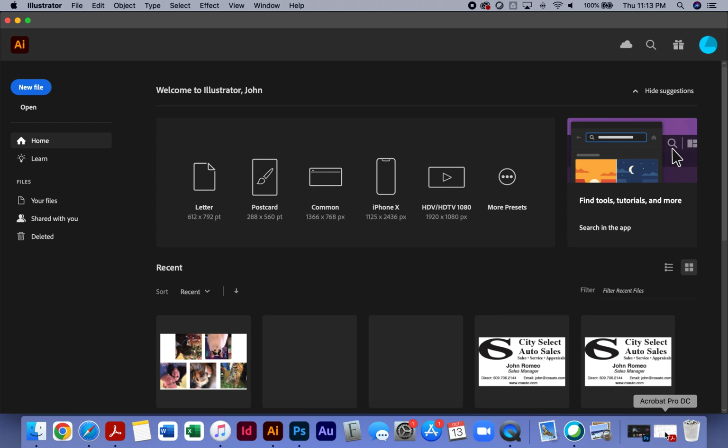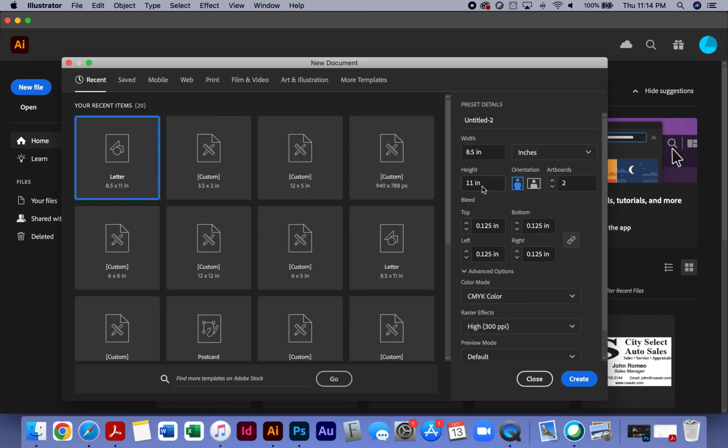So we're going to create a new document, Command N for new, and I'm going to set my parameters at 7 inches for width and 10 inches for height. And we're going to have an 1/8 of an inch bleed all around, because when these are printed, the images are going to be bleeding over the edges. We have bleeds because when they're printed and then cut down, there's no white showing, and white's very tacky and it just doesn't look good. So that's why we have bleeds.